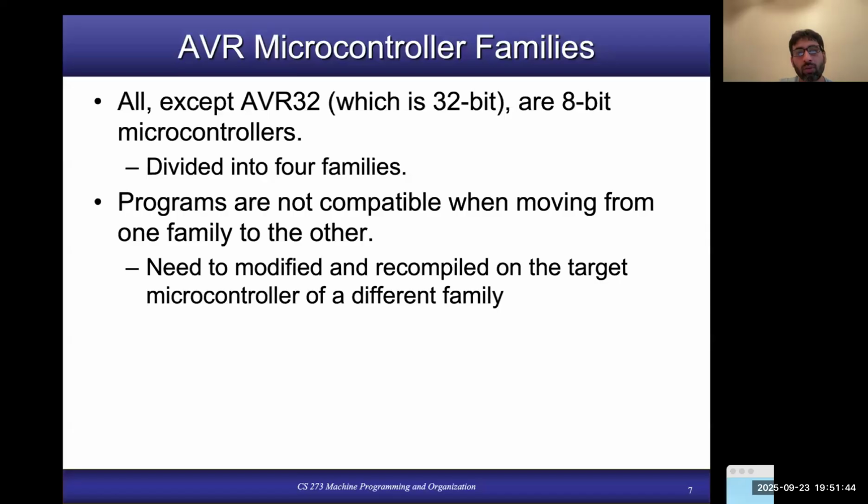The problem with AVR microcontrollers is that they are not compatible across families, which basically means that you cannot run the same code as it is, written for one microcontroller in a given family, on an AVR microcontroller in a different family. So you will need to modify and recompile on the target microcontroller of a different family before you can run it.